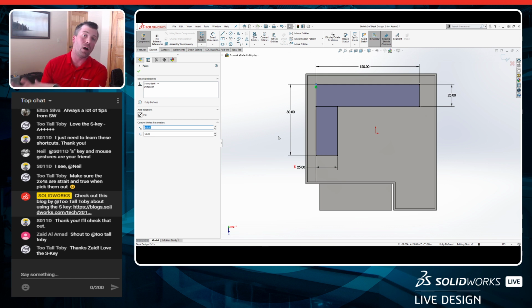So it's referencing that other part, the office that I built, and now it knows where it is in space relative to that office. So again, if we blew out a wall and stretched this or whatever it might be, that would now possibly modify the sketch that I created or the position of it. So just keep that in mind when you're working in this type of design from a top-down approach, that if we create these relationships to other parts, if they change, they can update. So just be aware. So again, I'm going to disable that. Let's just back up one little bit. We'll disable the relationship. And so far, this looks good.